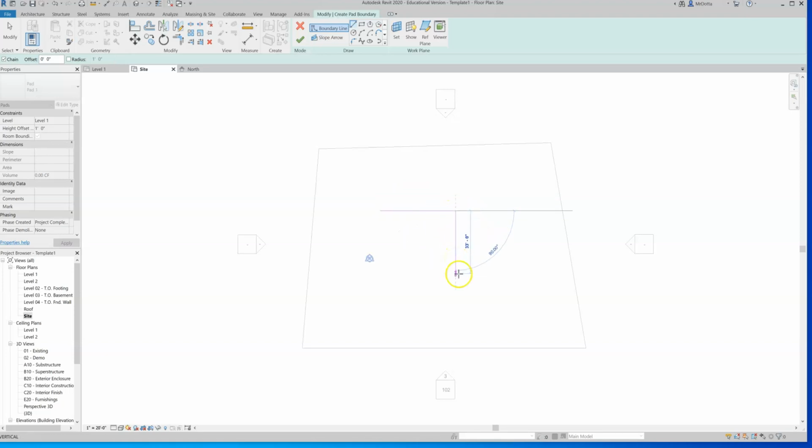Okay, now I'm going to come down and let's make it about 35 feet. Let's come across here. So notice what else it does is I come over here with my mouse and I line it up with that edge. Notice, again, those dotted lines, those dashed lines. It finds the adjacent endpoint. It finds the same length. So I don't have to type in the value again. I can simply click right here. It matches that same line up top. So as long as that dashed line shows up, I can click. I can come back up to here and I can snap to the endpoint.